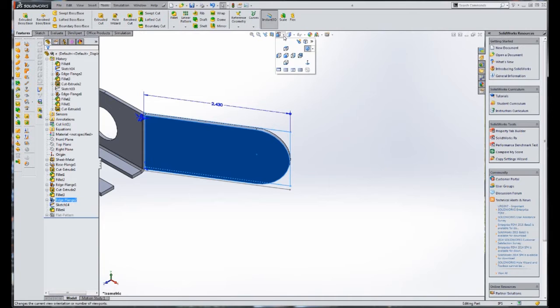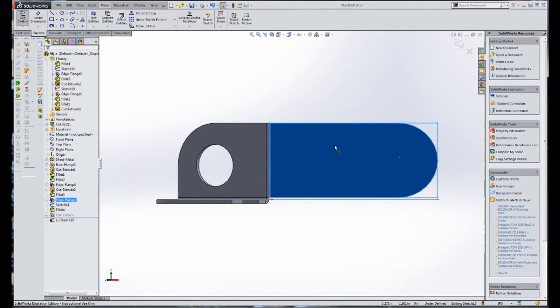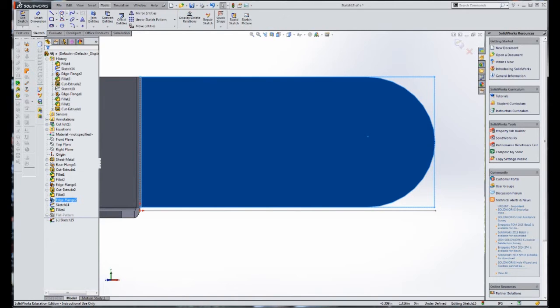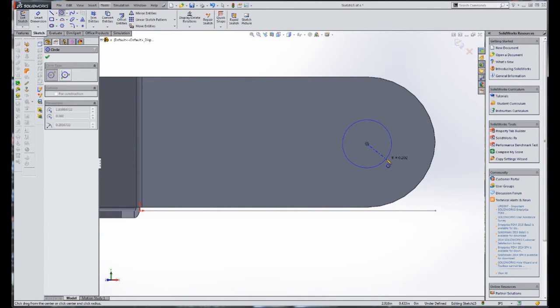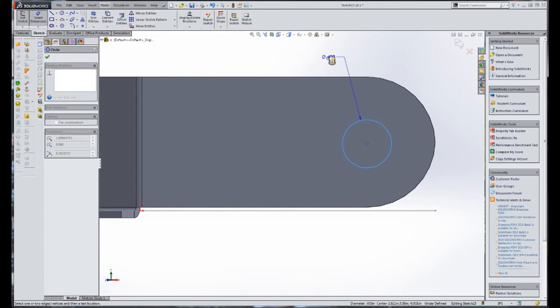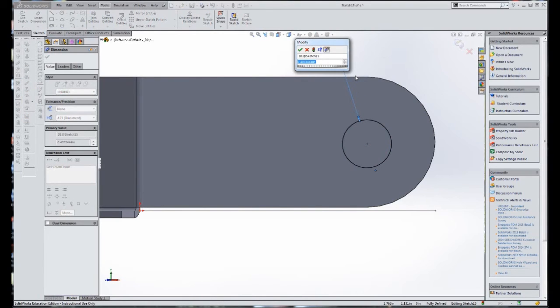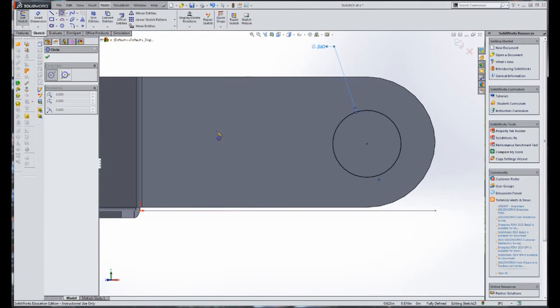So here we want to do a normal to. Okay, that means it's going to face you, and now you can see this is a bit elliptical on the left, and then we're going to sketch. We know that the first circle is going to be right at the center of these radii because of the 56. And we know that it has a size of 0.28, and that's a radius, so it's 0.28 times 2, okay, which is 0.560.